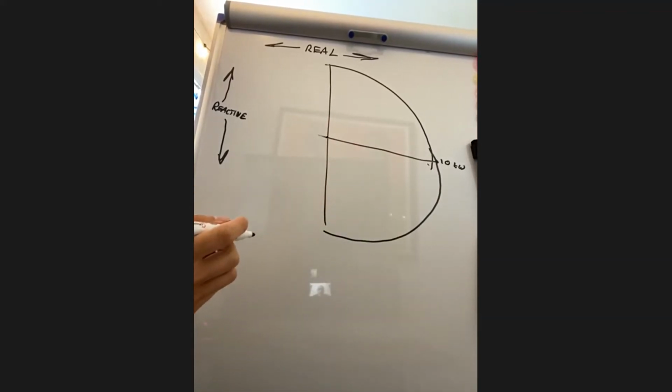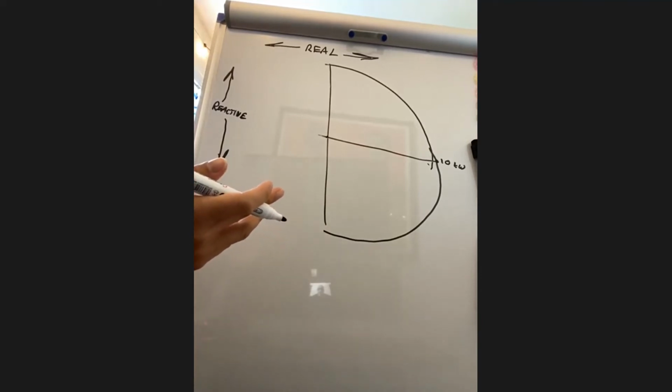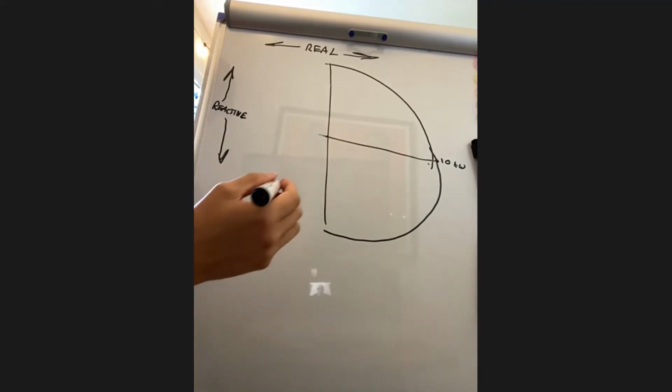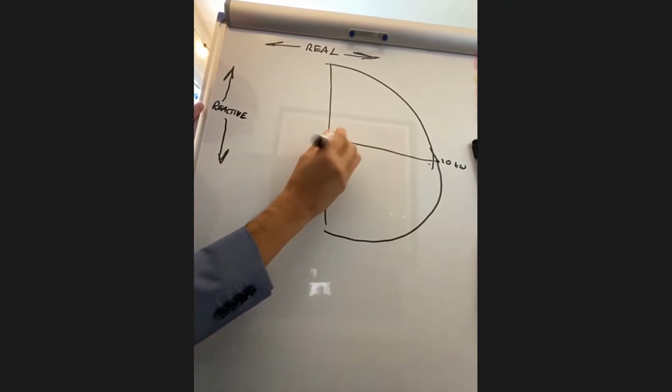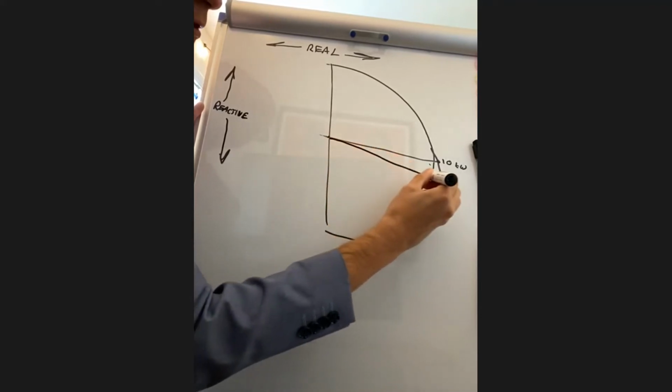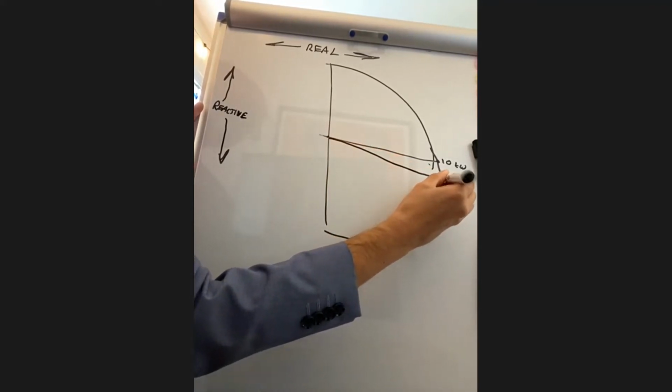And then when a smart inverter is loaded to have a volt-var curve or a fixed power factor setting or something like that, then what happens is you're no longer just following this line, but rather you change the angle. So let's say we could change the angle so the new line looks like that.